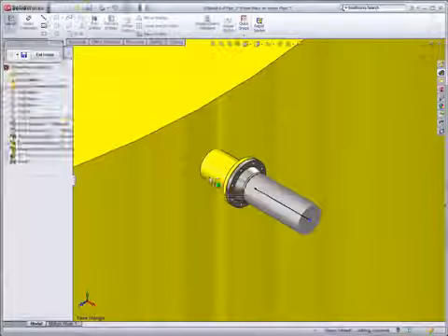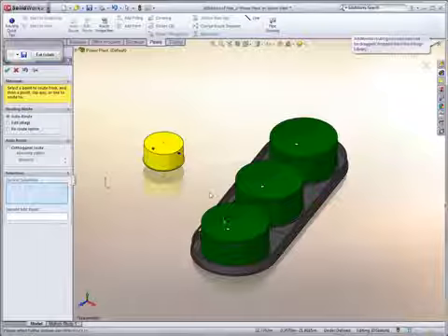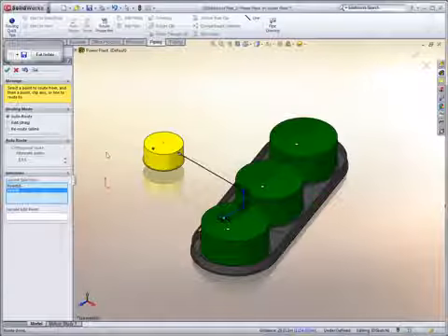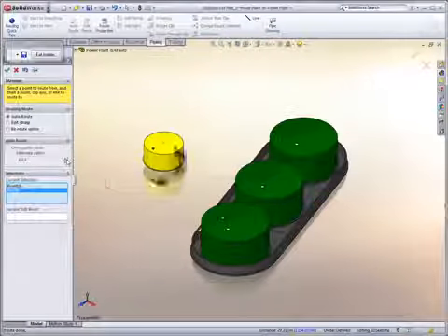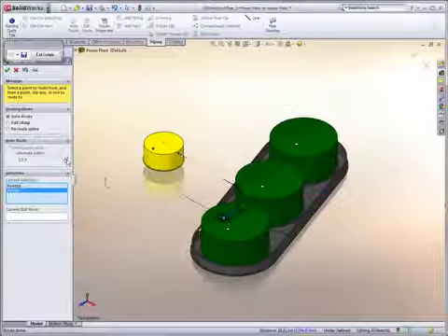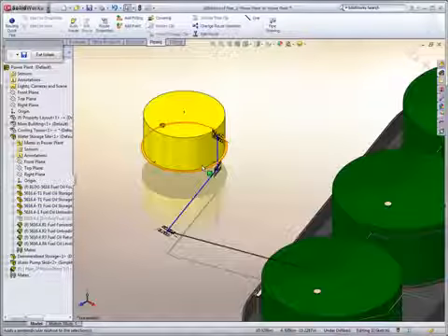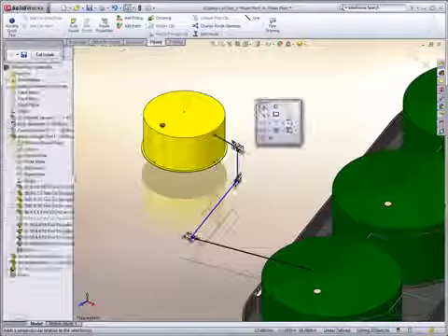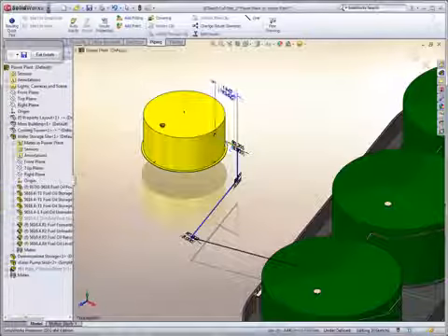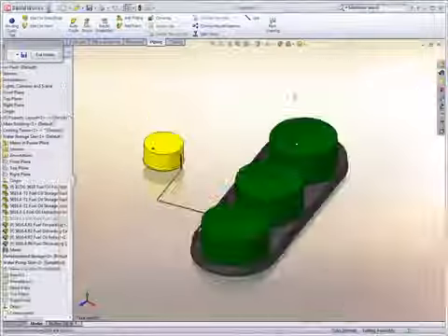When generating a pipe route or a spool, engineers and designers simply need to select connecting ends of their design and let SolidWorks auto-route capabilities do the bulk of the work for them. This saves a great deal of time in getting an initial layout completed. We could, if we wanted, further refine the route to whatever our unique demands might be. SolidWorks then generates all of the individual pipes for the design.